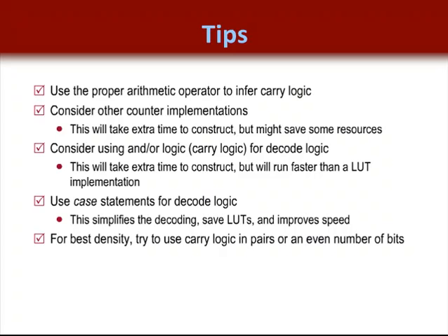Okay? And as we mentioned, some of the alternatives include one-hot, and that's probably one of the most commonly used ones, as well as Johnson and LFSR. They'll take extra time to construct, but might save some resources and improve the speed of your design.